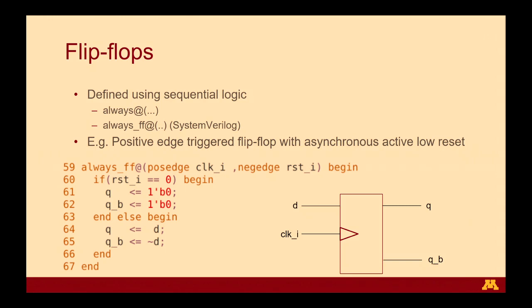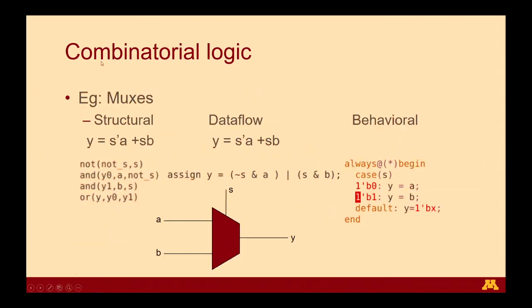The last block we're going to talk about here is flip-flops. In general, a flip-flop is similar in design to the combinatorial logic, but instead of having an always @(*) block. What I forgot to mention is that when you have always @ star, what's within the brackets is the sensitivity list. Star indicates that anything in the block is part of the sensitivity list. So if S changes, A changes, or B changes, this entire block will be triggered to get a result.